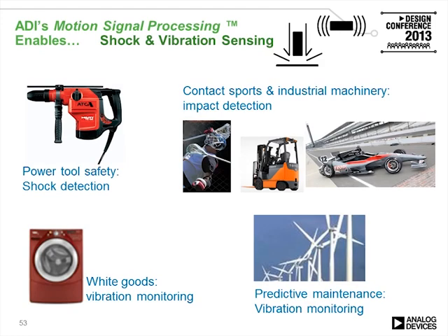Some applications where shock detection is very useful are things like abuse detection, so did you drop what I gave you, and concussion detection, which is becoming very visible in today's sports world. Vibration detection can help predict, for example, when bearings in a machine or in something that's rotating are not running smoothly. For example, when a washing machine isn't balanced, or say when a windmill is vibrating due to excessive wind.